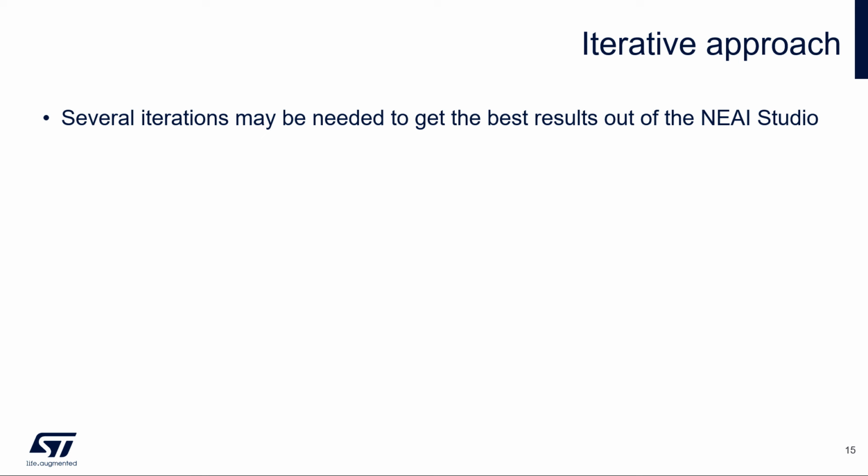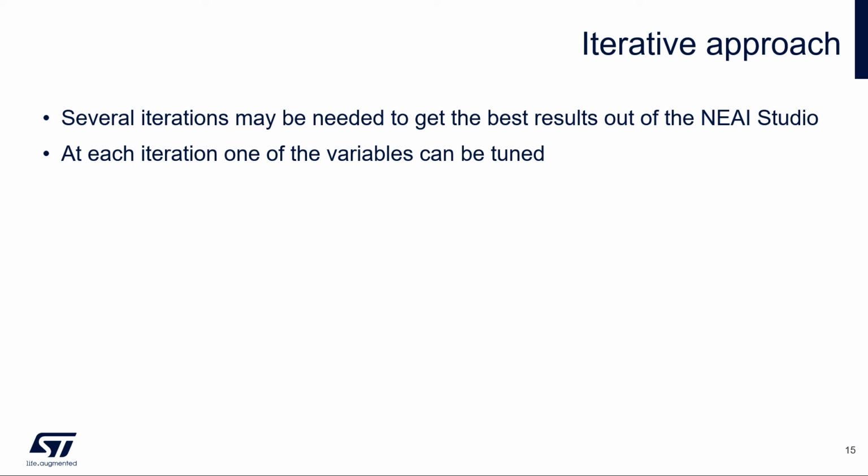Let's now close this chapter on an important aspect of the NanoEdge AI Studio workflow. Even if it is presented as a linear process, in practice, the data logging variables may not be the most suitable on the first attempt. We saw that there is no strict rule to set the ideal sensor output data rate or buffer size that are drastically linked to the use case. The NanoEdge AI Studio cannot do that either. However, using it in an iterative approach, it is a powerful tool to test and converge towards the ideal data logging environment.